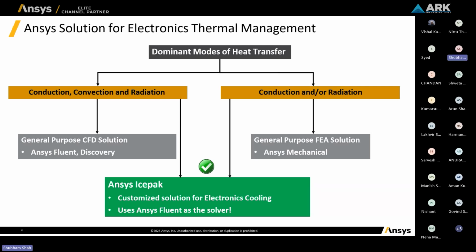When we talk about conduction and radiation specifically, these are also available in Ansys Mechanical, which is structural software. When your focus is structural analysis, fatigue analysis, modal analysis, Ansys Mechanical is there. In Ansys Mechanical, the convection mode of heat transfer is not available. It works on conduction and radiation.